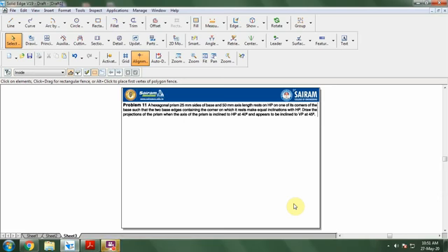Hi students, in this video I want to discuss the projection of a hexagonal prism. So let us consider a problem. A hexagonal prism, 25 mm sides of base, 50 mm axis length, rests on HP on one of its corners of the base such that the two base edges containing that corner on which it rests make equal inclination with HP.